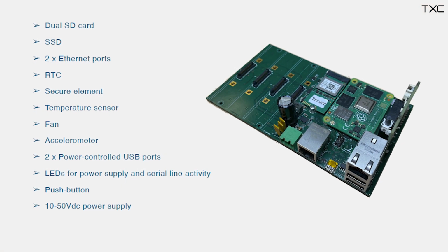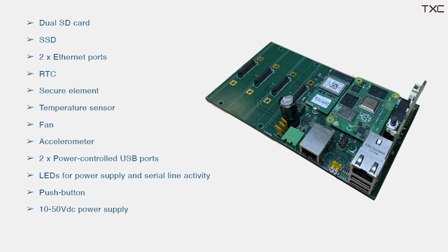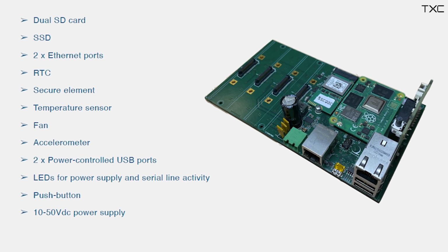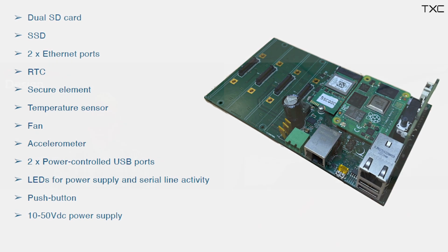The compute module offers more flexibility in the I/O architecture you put around the computing core, compared to the traditional Raspberry Pi. So you can replace or reposition the Ethernet and USB ports. You can avoid using the SD slot on the Raspberry Pi and do something more. And that's exactly what we've done here.